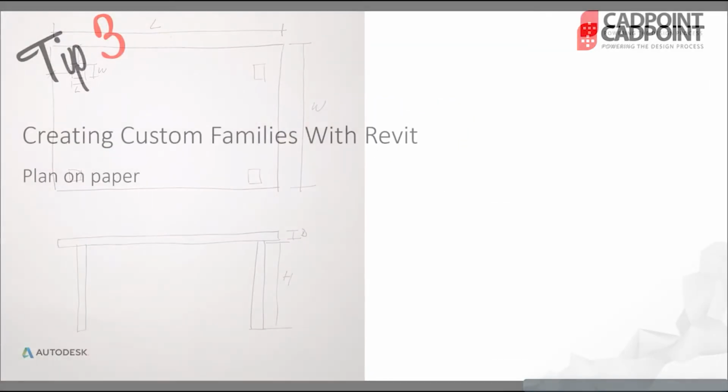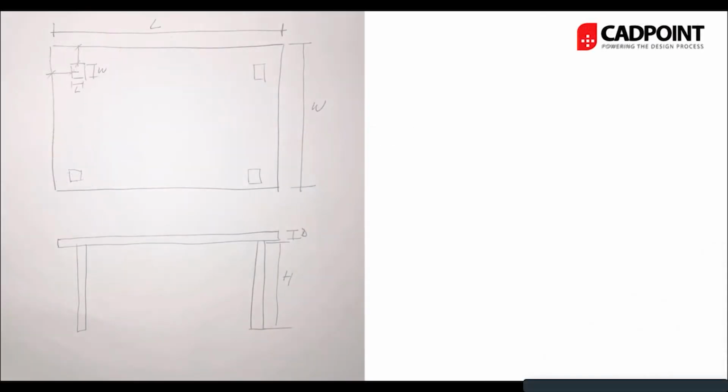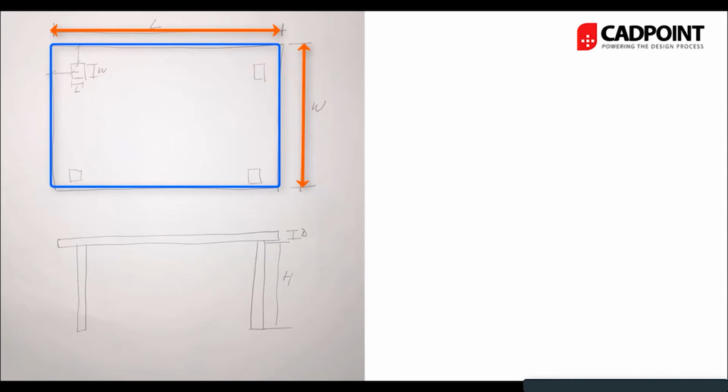What's quite important is to plan out your family before you actually create any geometry or even start a Revit template file. In this, we're going to create a fairly basic table, and we're going to give it a number of parameters. On the left hand side, we've got a very basic paper sketch of a tabletop in plan view at the very top, and on the bottom we've got an elevation showing the tabletop and the height of the legs perhaps. Within this family, we know we want to be able to create some sort of tabletop. We want to give it a length and a width, and we want to be able to control that length and width. The way we'll do that is by using reference planes and constraints.